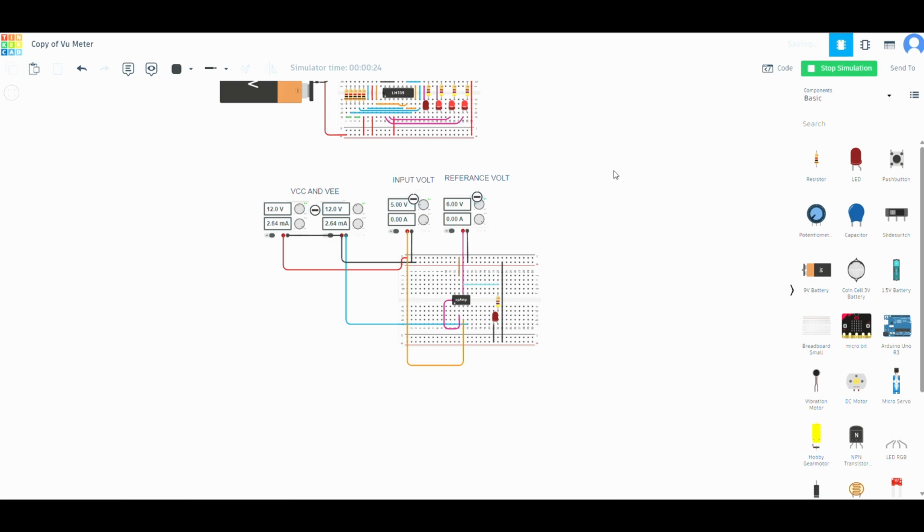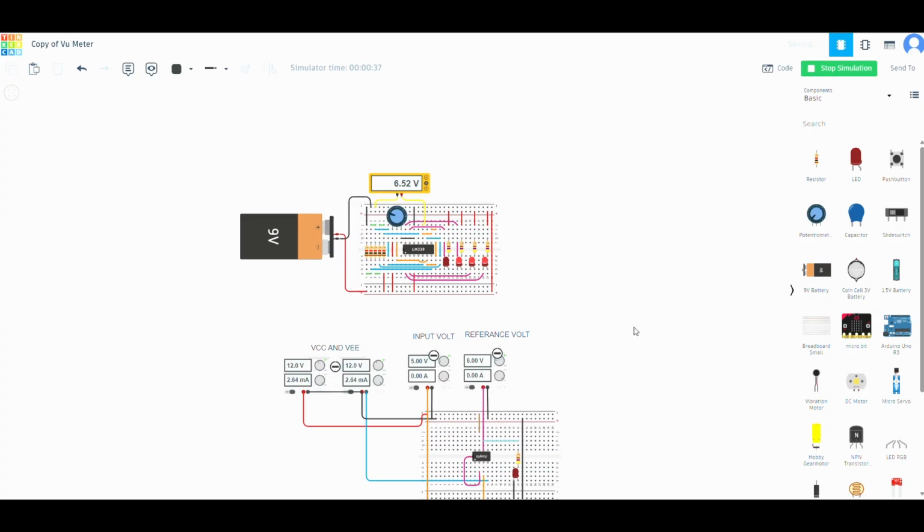When we thought of making this circuit, we required 10 output LEDs, but it is not practical to use an IC741 for this. So we shifted to the LM339, which is a quad comparator IC. In this IC there are 4 op-amp comparators. So we are using the LM339, and we made this circuit to show how it will work.